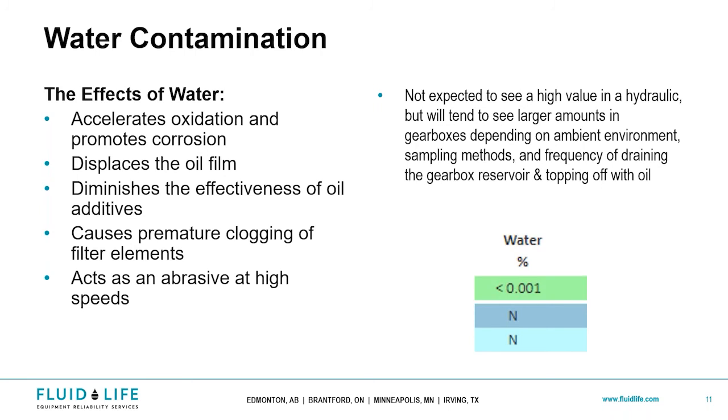Water can be present as free, as we're talking about with different chemical properties and oil and water not mixing, but that doesn't necessarily mean it can't be dissolved or what we call emulsified, where it mixes in a little bit. So keep that in mind. Free water is pretty easy to spot because it'll accumulate at the bottom of the loop system, but sometimes it can mix in with your oil and degrade the ability for the oil to work the way it's supposed to.